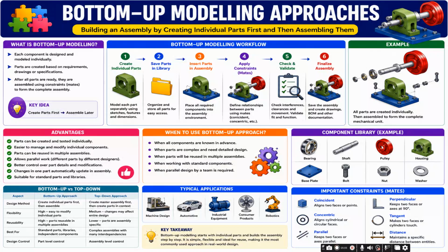After all the parts are ready, they are assembled using constraints made for the complete assembly. So the key idea is to create the parts first, then assemble them layer by layer. The bottom-up modeling workflow: create individual parts, save parts in a library, insert parts in the assembly, apply constraints, add, check,